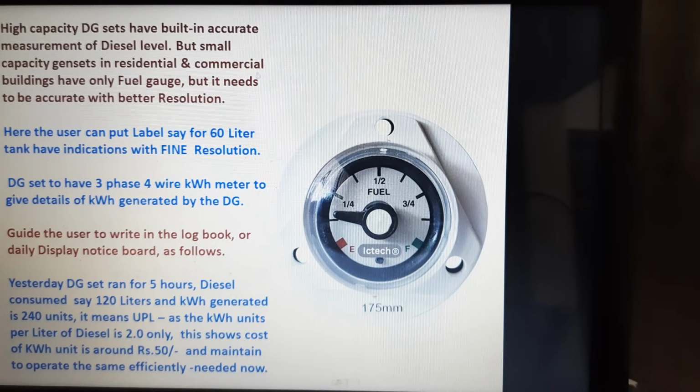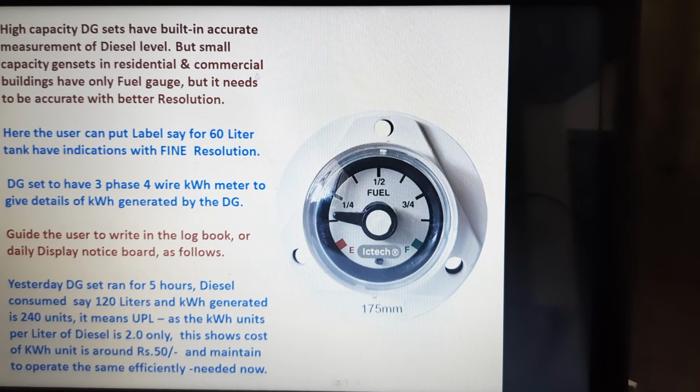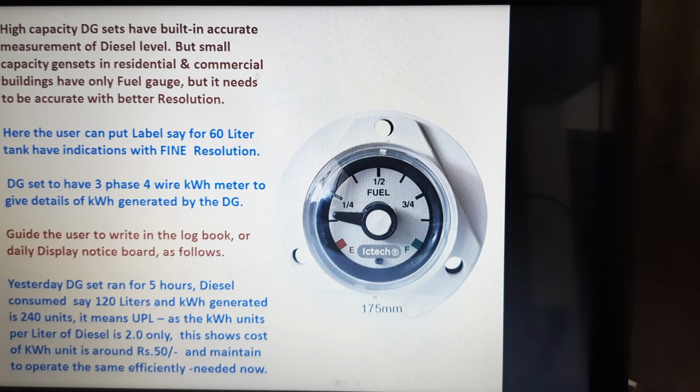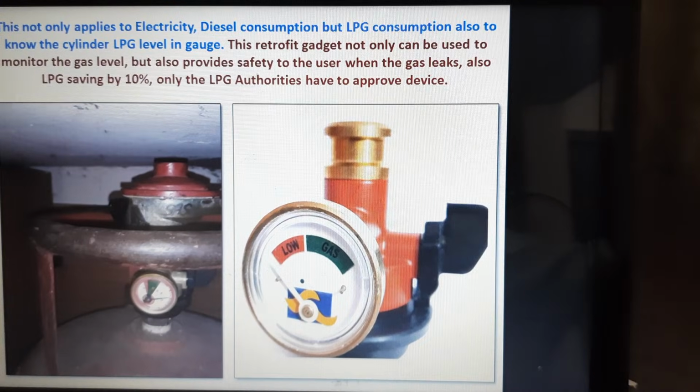Also, leave alone the analog type of fuel gauge; a digital type diesel level gauge is also available now, and it costs only a few thousands. Definitely this will give you an input of the diesel in liters consumed for the genset run hours for the day and how many kWh delivered. This is a health parameter. This parameter needs to be monitored during the routine daily running of the diesel set.